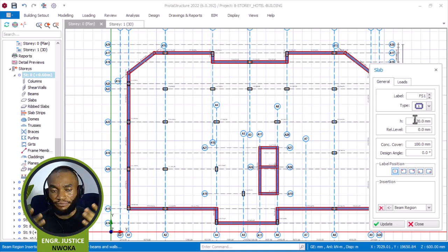That's because not everywhere are you going to slab. There are some parts you are going to fill with sharp sand, then you use a minimal slab depth of 200 to place the ground floor, like the lower floor level. That's fine for the slab, but the beams carry the weight of the structure.